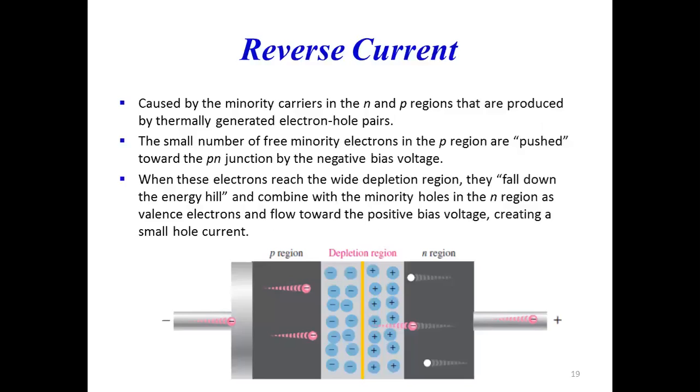Because of this very heavy electrical charge or potential at the depletion region, the minority carriers which are moving get accelerated. And because of their acceleration, those minority electrons will knock out a few electrons from the other covalent bonds. So what will happen? More and more electrons will be present in the circuit.